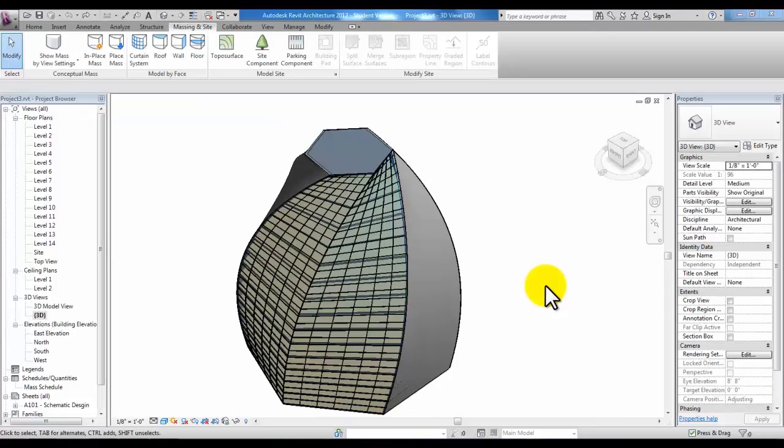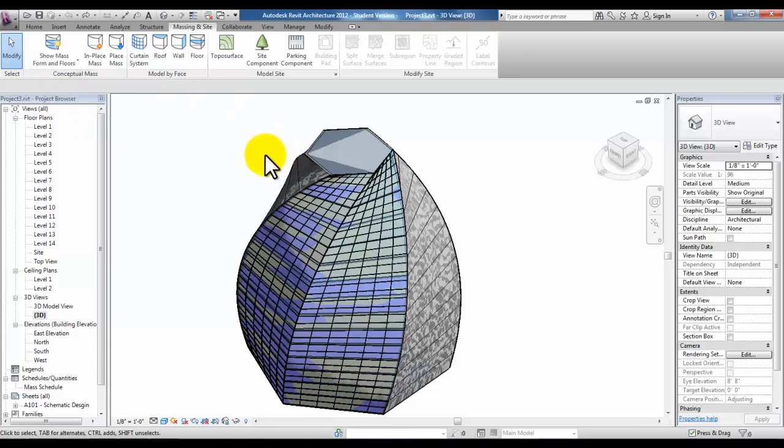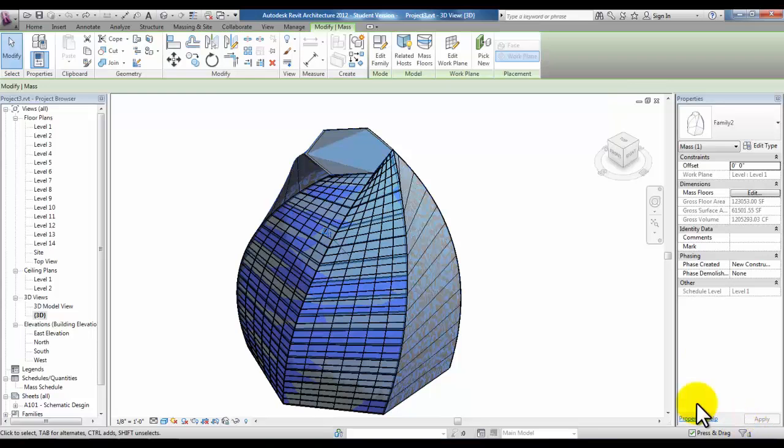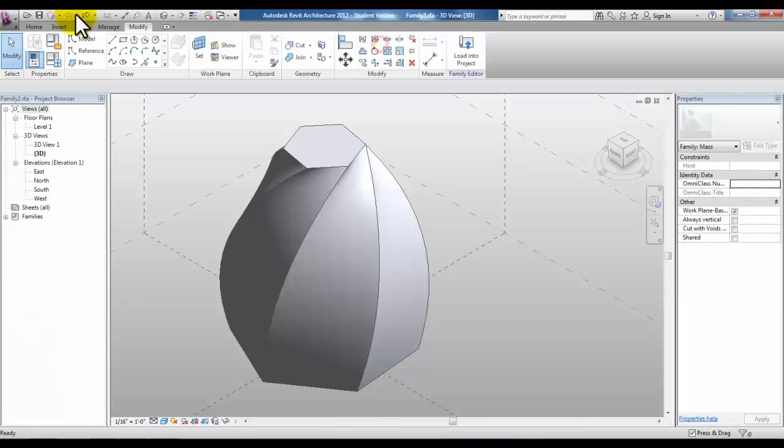I came back into the video here to show you that even after you modify the mask, you can update the faces. So here I can turn the mask back on, and then with the family open, I can tab to select the family or use the filter tool and then pick Edit Family. If you don't have the family open, when you pick Edit Family, you'll see a different view. To go back to the family, I could have used Control Tab also.